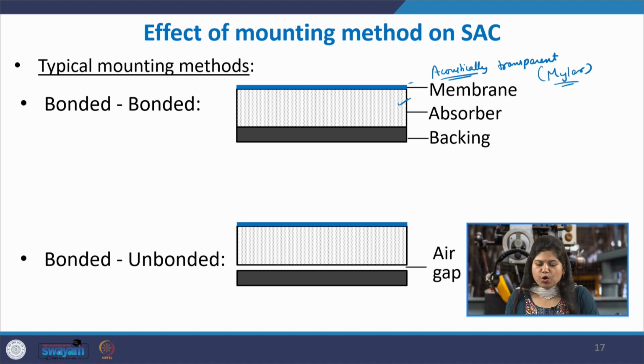And then you have the absorber followed by a backing, so that whatever sound transmission remains finally reaches the backing and further reduction takes place, so that the transmission goes down even further. That is why you have a barrier backing, to make the transmission go down even further.